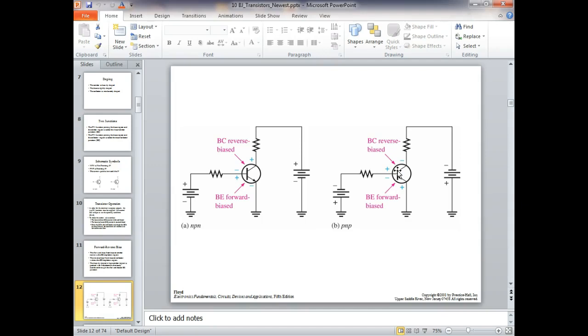So what's the difference between the function of a rheostat in the circuit and the function of a potentiometer in the circuit? They're both what we call variable resistors, but if they did the same thing, then we wouldn't have two types, right? So what's the difference? What does a rheostat do, and what does a potentiometer do? Well, we use potentiometers for resistance. We use resistors for resistance. So what's the function of a rheostat? Well, a rheostat controls a current. A potentiometer controls a voltage.